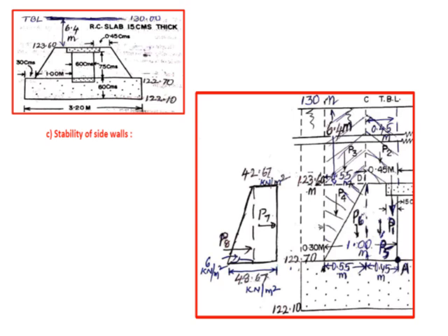So from the dead load, the span is 0.9 meters. WL by 2 will give the reaction. So that reaction, the slab as well as the weight of the fill is transferred as reactions, which is P1, which is WL by 2. And we also calculate the weight of the earth, that is P2.